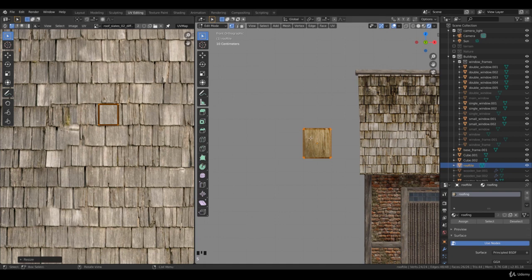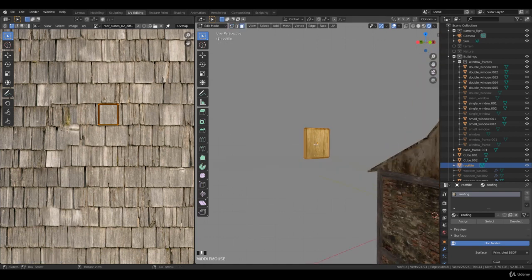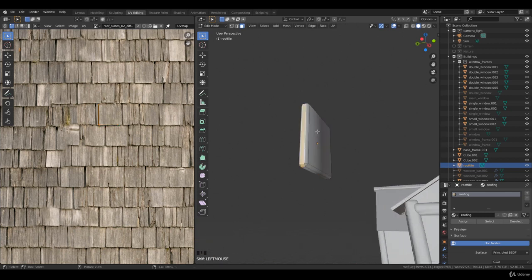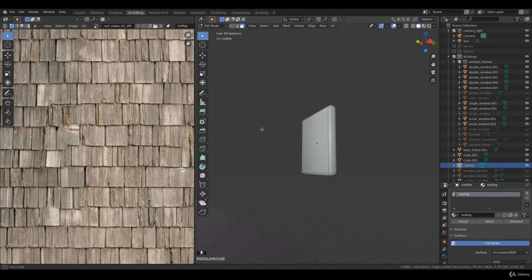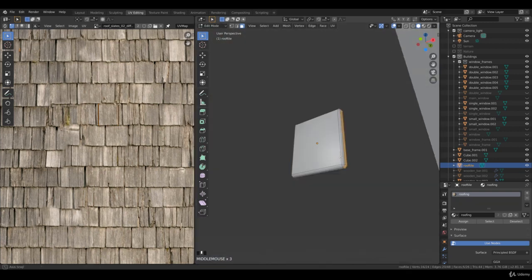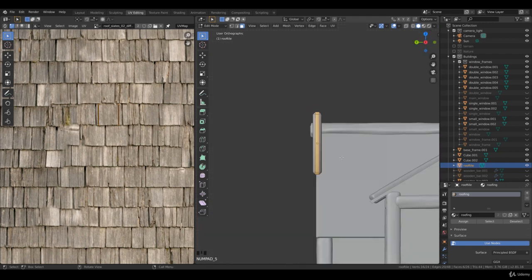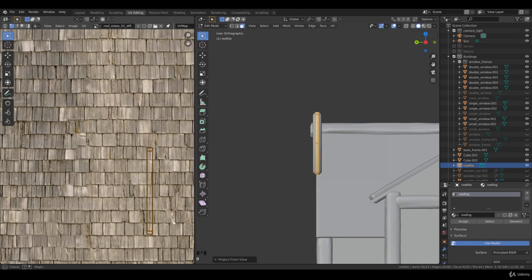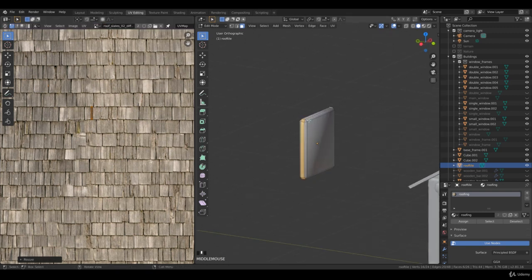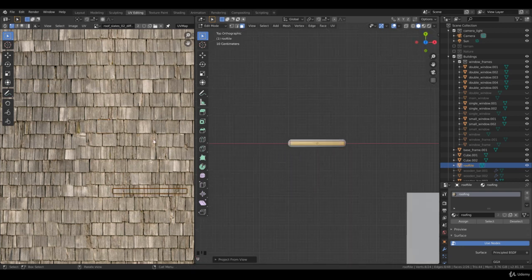something like this. Then you go to the face selection mode, go to solid, and you want to select the sides, these, yes, and go to this part, make a projection, yes, just make it smaller, size just a little bit, putting it right there. And I want to have a top projection, and then we have covered all the sides of the roof tile. I mean, you won't really see this, but let's say you just want to have it.